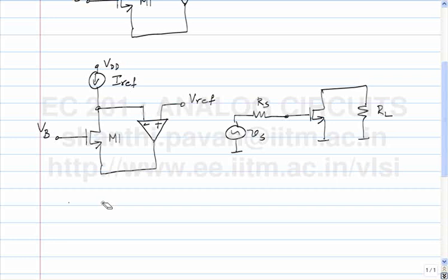Then we have to look at what we have and see what is there in the circuit that sets the operating point, which we don't want. We need to get rid of that stuff. The first thing that we need to do is add RS. Okay, so we need to generate VB. One simple way of generating VB, some battery voltage, would be to use a potential divider.